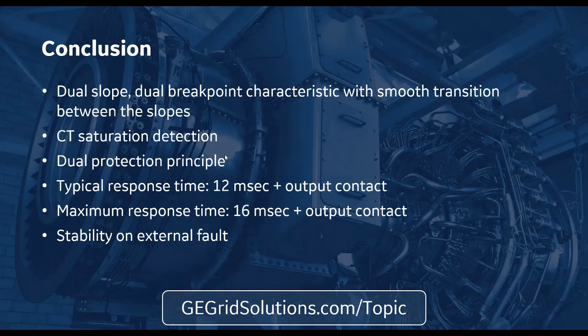Somebody asked about transformer differential. Transformer differential is basically bus differential, but the additional thing we need to take care of is the winding ratio of the transformer. So we need to compensate for the winding ratio, and we need to consider transformer inrush. When we energize a transformer, there's a transient inrush into the transformer, and this is the one case where Kirchhoff's law doesn't apply. Current in for an inrush condition does not equal current out. It's all current in for inrush. That can affect the differential because now it's seeing a differential current, and it could trip for transformer inrush.